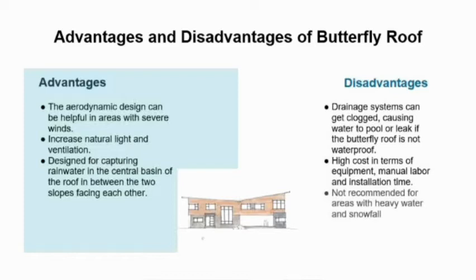The disadvantages of the butterfly roof: ensuring the butterfly roof is waterproof is very essential. The drainage system can get clogged, causing water to pool or leak. This will weaken the pillars over time, which can cause the roof to collapse. Then, the butterfly roof is extremely complex and difficult to install, which drives up both labor and material costs as well as installation times. While butterfly roofs are able to collect and either remove or reuse water, if they become clogged with debris or if a large amount of snow is allowed to collect on them, the roof can...